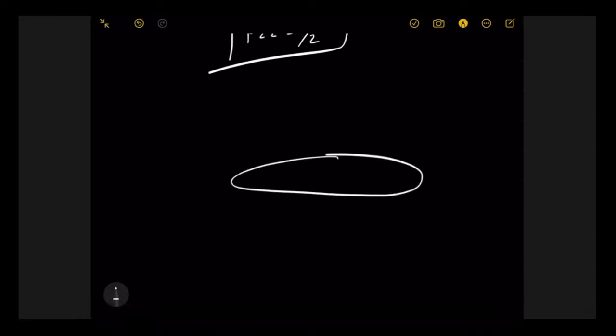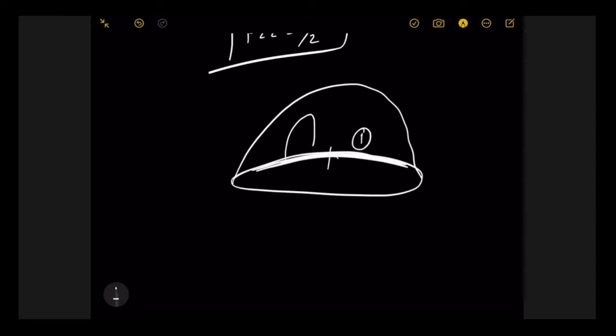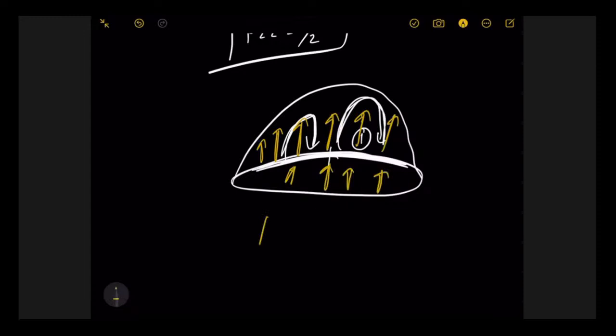This is the object like this. So when this object is moving from this section, this is object 1. So self view factor of 1 can't be like this. The rays can't go like this; it will always be going in this direction. What is the meaning of F11? From object 1, how much energy is going towards its own object 1?